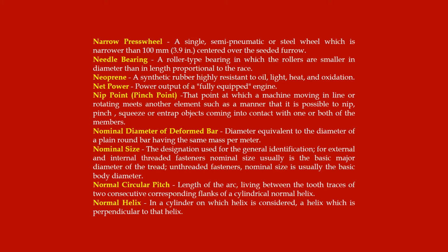Nip point or pinch point. That point at which a machine moving in line or rotating meets another element in such a manner that it is possible to nip, pinch, squeeze or entrap objects coming into contact with one or both of the members. Nominal diameter of deformed bar. Diameter equivalent to the diameter of a plain round bar having the same mass per meter. Nominal size. The designation used for the general identification. For external and internal threaded fasteners, nominal size usually is the basic major diameter of the thread. Unthreaded fasteners, nominal size is usually the basic body diameter.